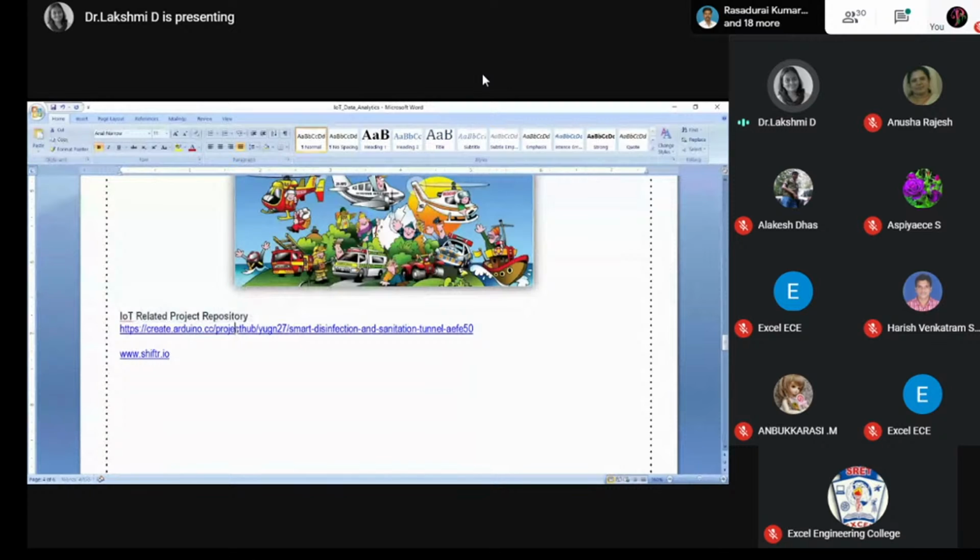Then here, if you look at the digital pins, most digital instruments and digital signal related projects depend on these kinds of pins. Whenever we touch upon analog, we need to look into this. There are 3 ground pins, one on this side and 2 on this side, a 3.3 volt power supply, and a 5 volt power supply available here.